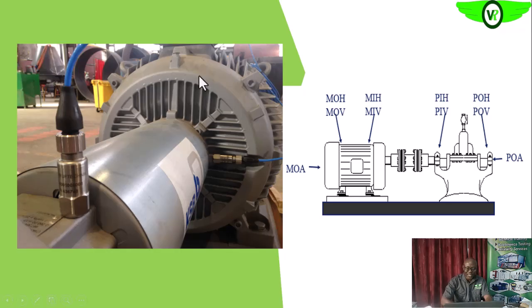So we can use this spot, placing our probe directly into the spot. As you see this probe now, this base, we attach it to this end so that the probe will be parallel to this coupling, making the direction parallel to the direction of the shaft in the electric motor. So that becomes our axial direction.